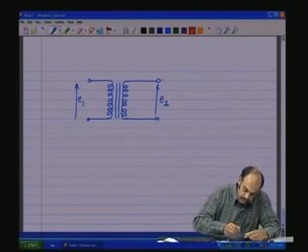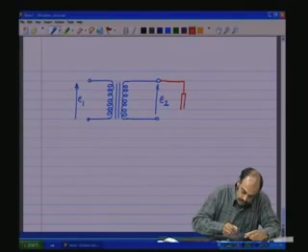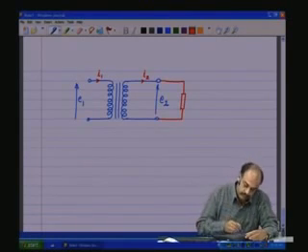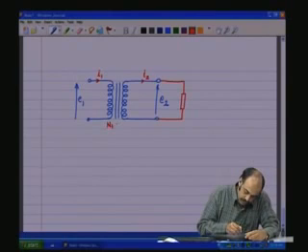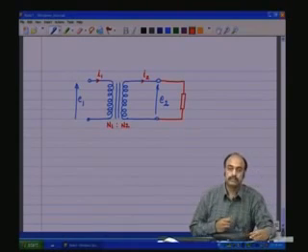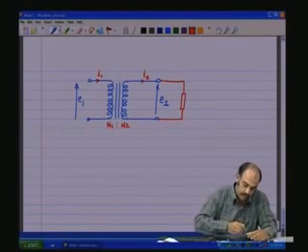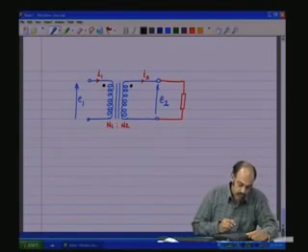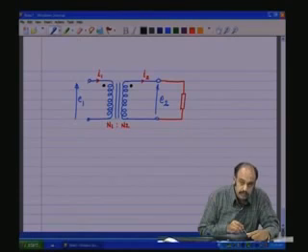So, let us now do that job of connecting a load across the secondary. This means there is going to be a current I1, there is going to be a current I2 in the secondary, and this is N1 is to N2. Now, let us also have the dot polarities like that. So, which means when the dot side is positive, the dot side here is also positive.